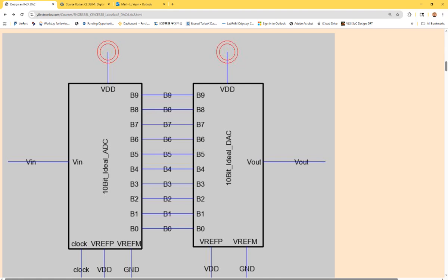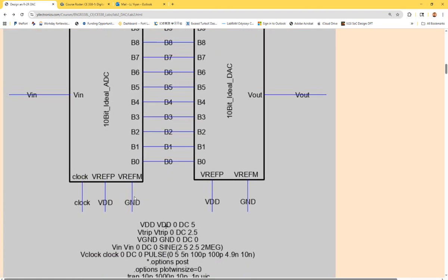Even though this symbol doesn't have a name with it, the hidden name of it is actually VDD. Same for ground. I don't have a ground symbol here, but if you type a GND, it will be directly shorted to the ground symbol, even though we don't have a ground symbol used in the schematic. So why is that important? Because you can see here, VDD.